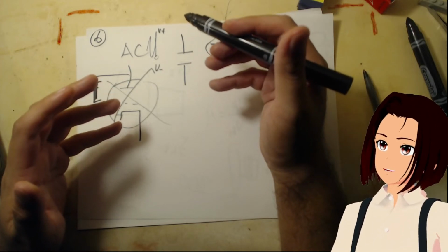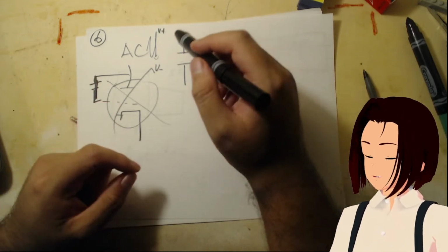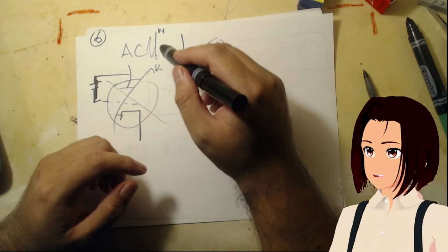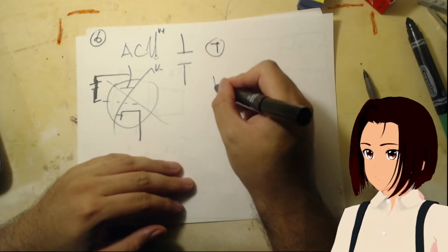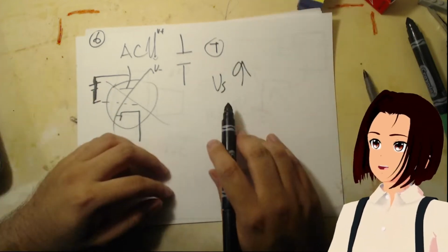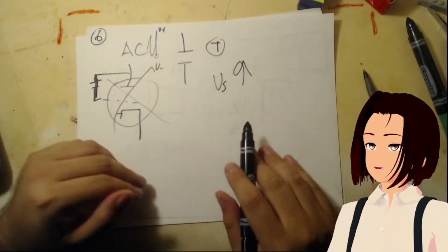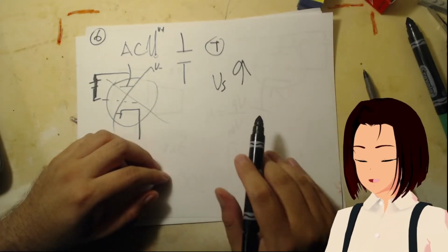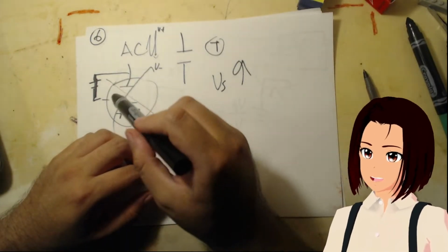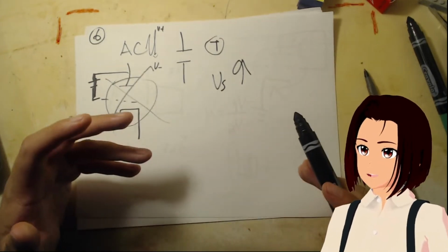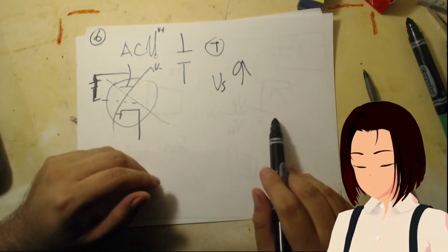If we use a really high frequency signal, like if Vs is really, really high, then this doesn't matter and the circuit doesn't work as we want. That's a really big downside. That capacitance really throws a wrench in some of the applications we would like.